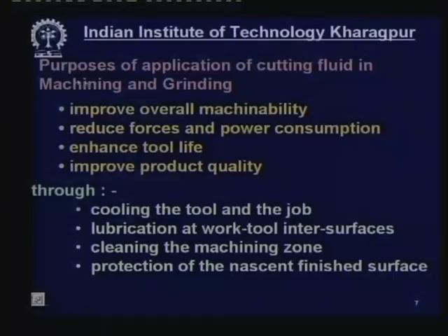Next, we find the purposes of application of cutting fluid in machining and grinding. Now, what are the purposes? Very clear. The aim of application is improvement of overall machinability, ease of machining, reducing cutting forces and power consumption. That will help in saving energy as well as reducing heat generation.